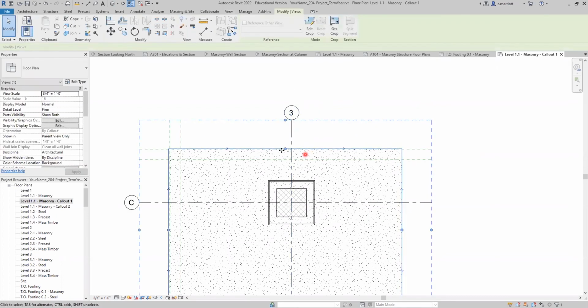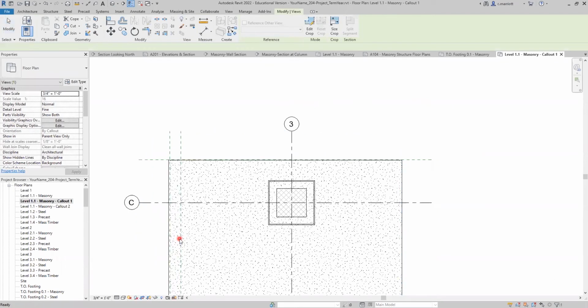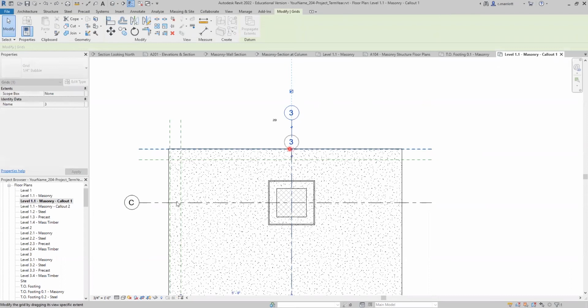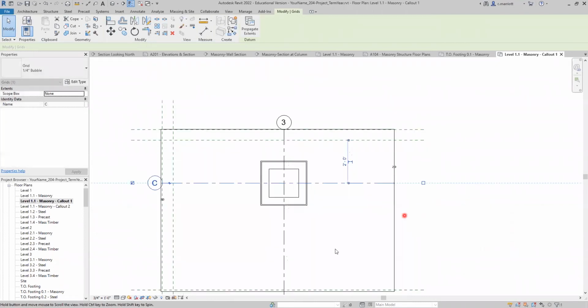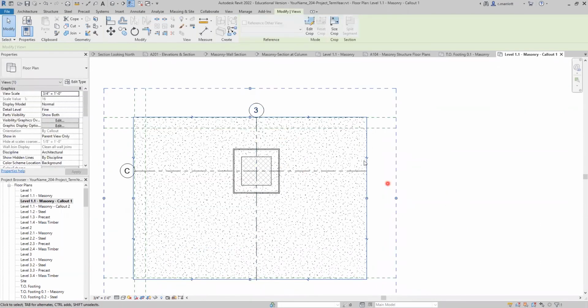And we're going to do a couple of things. We're going to drag that clipping plane in here. Oops. You know what? You're going to need to do this step first. Click on the column bubble, bring it down, bring those in first, and then drag the clipping plane to be a little bit smaller. Pull all of these in. Click on clipping plane, and I will bring these into my reference lines.